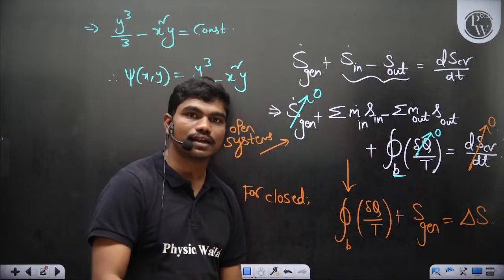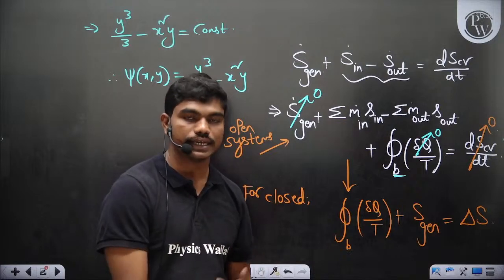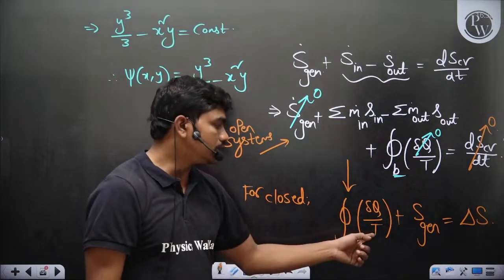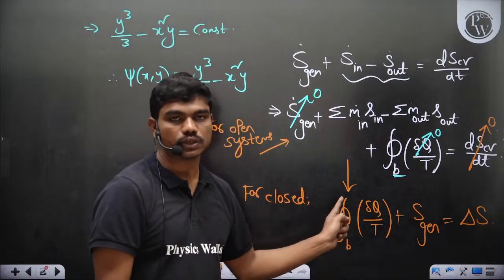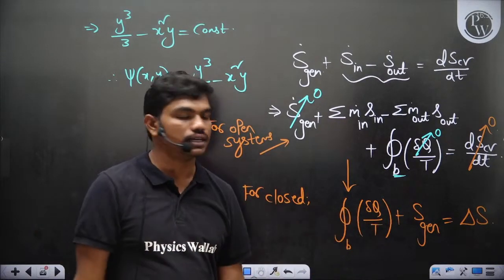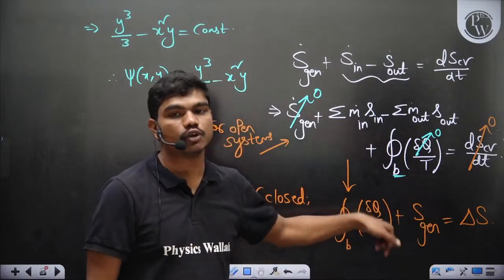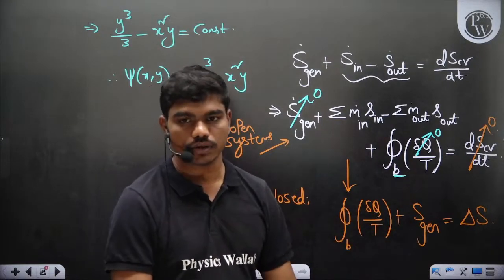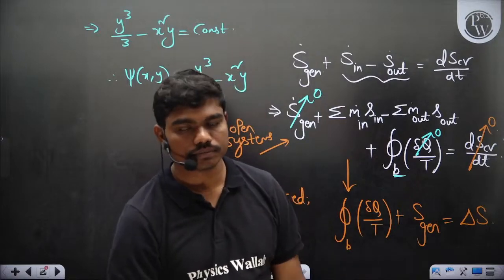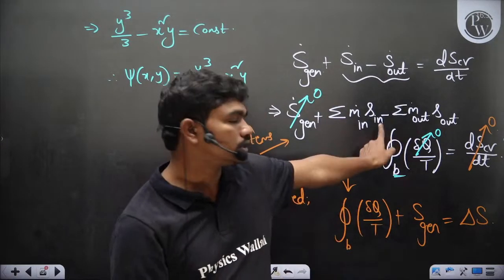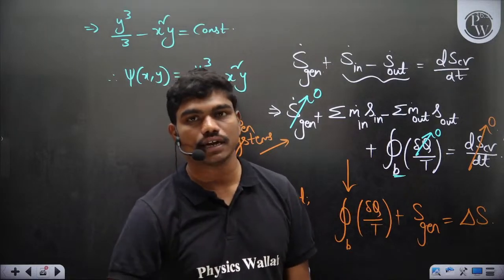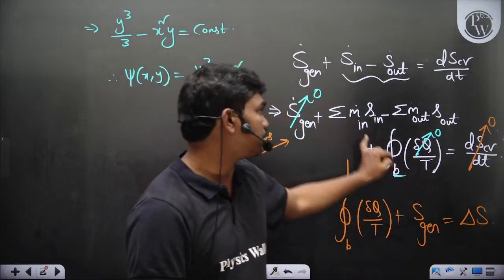And if you have a constant temperature, like you see in the case of thermal reservoirs, in Carnot cycles, wherever, then this T is constant, it comes out of the integral. So the integration of small amounts of heat, the summation of all the heats, gives you delta S is equal to delta Q by T actually. Or Q by T, whatever notation you use. Clear? This is the equation which talks about all the entropy questions. Each and every entropy question can be solved using this equation.